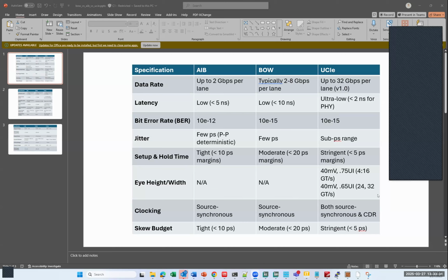One of the reasons for using this, apart from setting up SI simulation, is even basic interface checking. When you have two chiplets, at the very basic level you want to know that on both ends it's matched in terms of functionality. If one IP expects one thing and the other expects something else, obviously these cannot be matched. It will not work. Not interoperable. Exactly. I want to understand that a little bit next time.